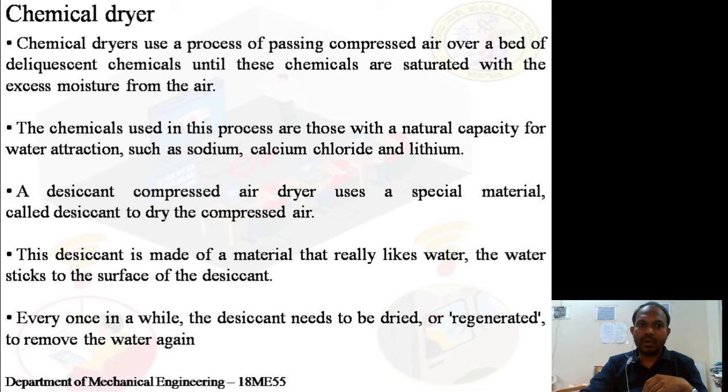Under normal conditions, heatless desiccant dryers house a desiccant material in two adjacent tanks, one next to the other, called the drying tower and the regenerating tower. Moisture in the compressed air flows into the drying tower first, then passes over and binds to the porous desiccants.